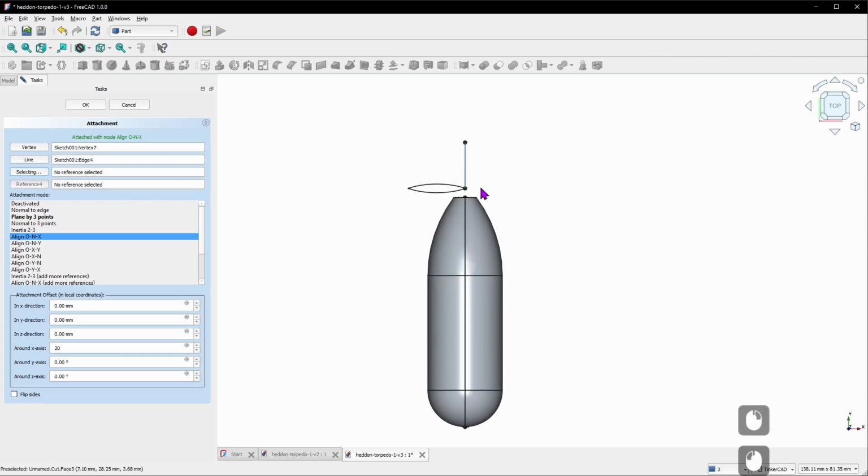Now, the other thing I want to do is I want to lean it back this direction. That is on the y-axis. Let's say 20 degrees. But that brought it forward. So you can always go negative here, and let's use a negative 20 and send it back.